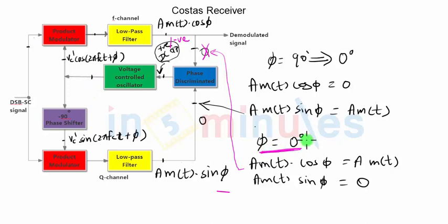degrees. So for any other value of phase between 90 and 0 degrees, there will be a DC signal generated between maximum positive and minimum negative values, and that DC signal will keep on changing the phase of the output carrier signal. And this phase correction will keep on taking place till the time the phase becomes equal to 0, the output is the minimum negative value, and the phase correction stops.